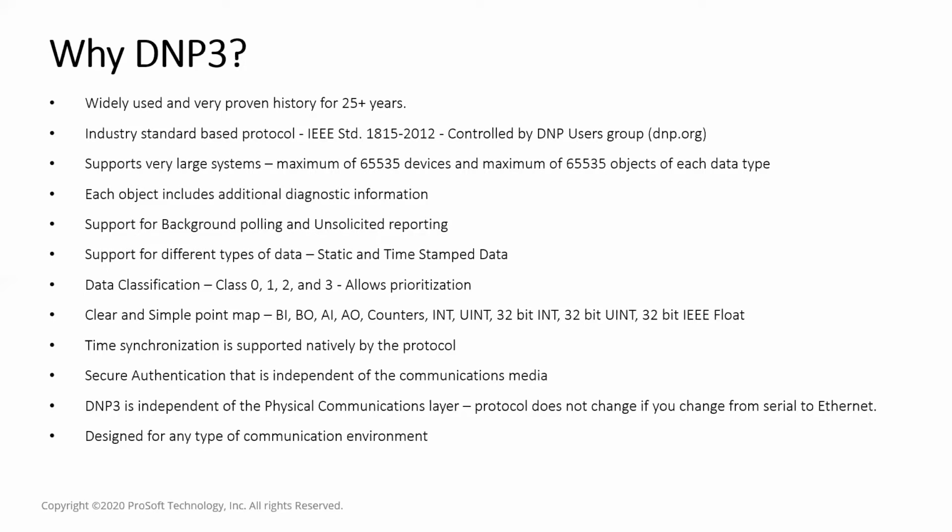And typically in many of the older systems, and especially in Modbus, for example, it's a poll-only system. So it is continuously going around asking for, give me your data, give me your data, give me your data. And that might work if you've got a small system, but if you've got a large system, that's not a very efficient use. You'll start to miss a lot of data.